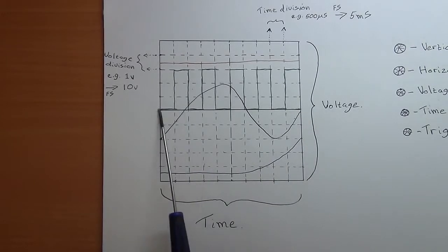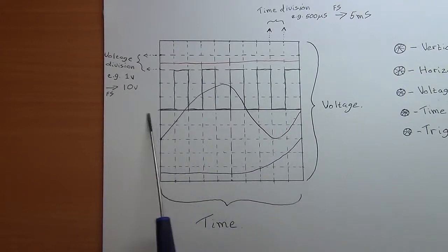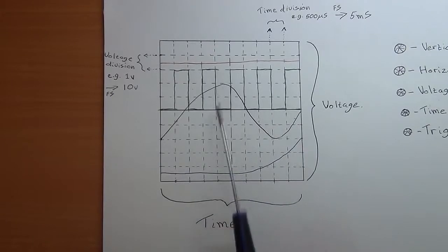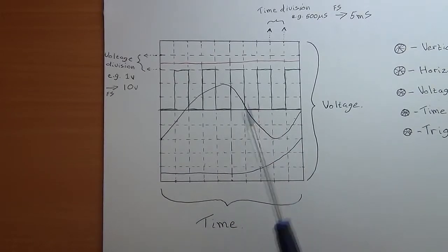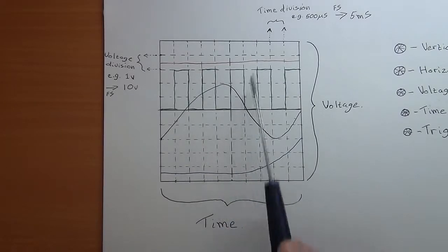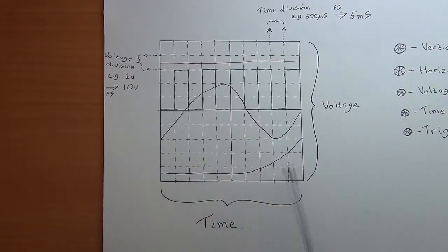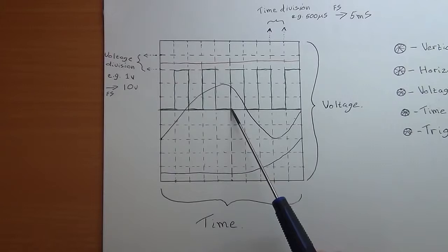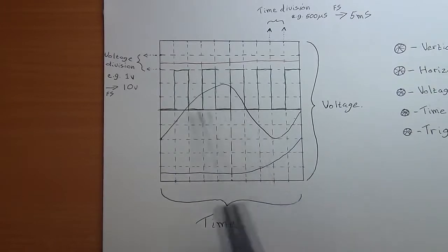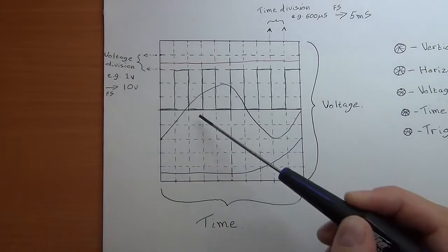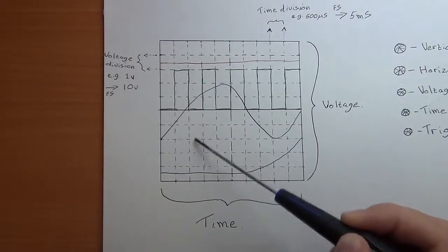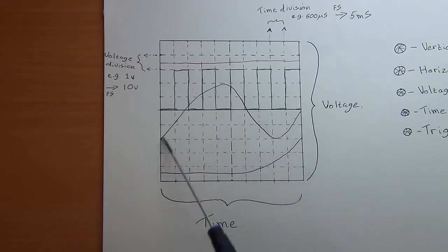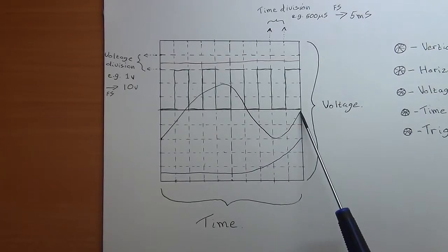Now, something else to highlight is that you have a kind of middle line on your oscilloscope, which in essence represents your 0 volt line. So above would be positive, below would be negative. But that's also relative, because you can make adjustments to pull a signal into your frame of view within the display and then make measurements. So you don't necessarily have to worry about that being the negative or your 0 line, because you can count the divisions when you want to take measurements of a signal. But this would obviously represent an alternating or a sinusoidal signal that's coming up and down.